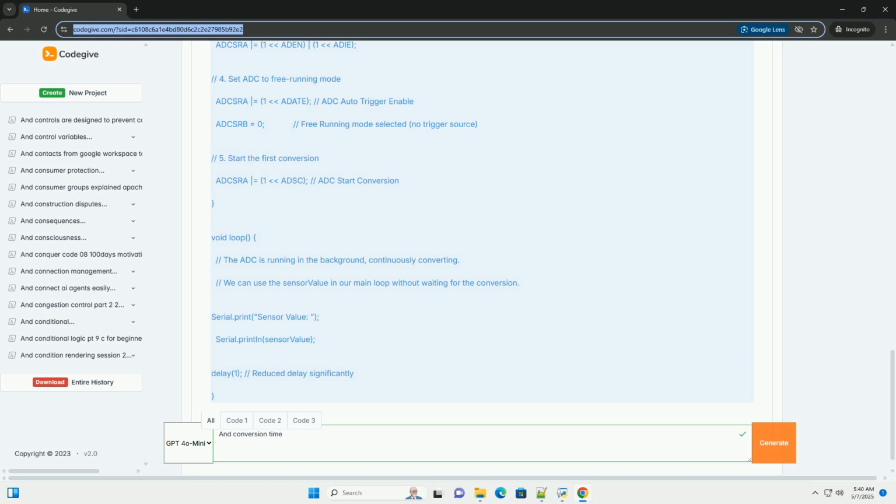4. Code examples and optimization strategies. Let's illustrate how to configure and use an ADC, along with optimization techniques, using Arduino, ATmega328P, as an example. The principles apply to other microcontrollers as well. 4.1. Basic ADC usage, Arduino. This is the simplest way to read an analog value using the analogRead function. However, it doesn't provide much control over the ADC's configuration and conversion time.